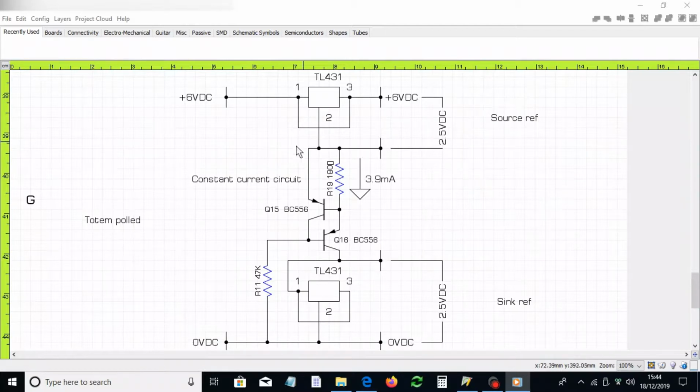In the middle of the two, instead of a resistive dropper, I've gone for, again, the constant current circuit I just showed you, and it works beautifully. The only problem is that the minimum voltage required would be somewhere around 5.5 to 6 volts, which put me off this circuit, although I quite like the look of it. It just doesn't go down low enough.